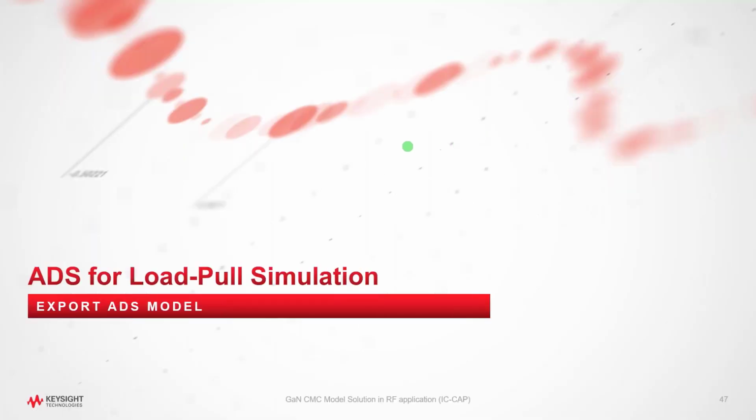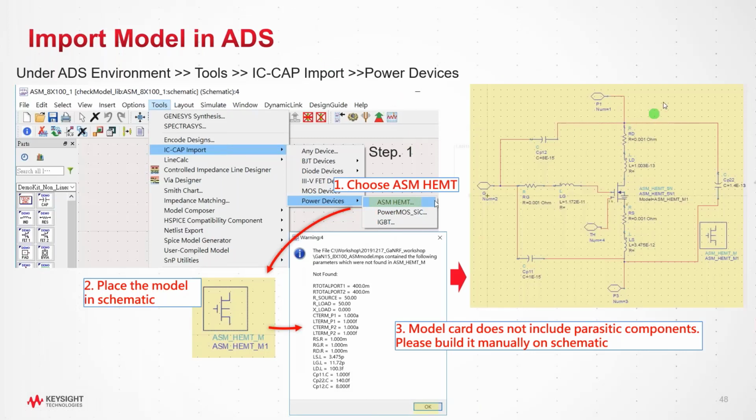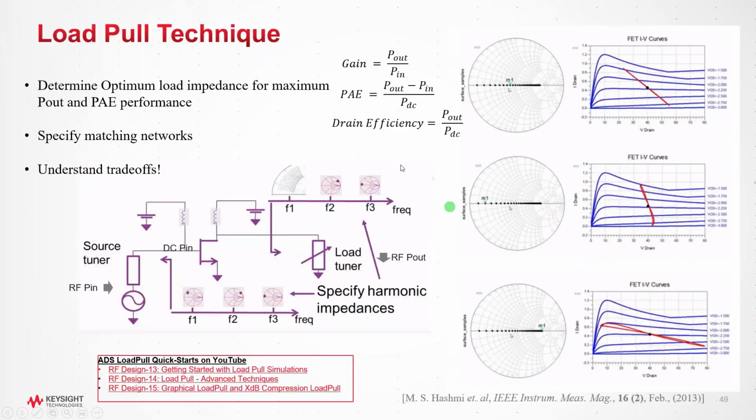All right, so as Abby said, if you guys can all see this, you can go into ADS and basically import that MPS, that model. Like if you did the ASM HEMT, and the MVSG has a similar extraction flow in IC-CAP, you just bring the MPS file, the model file, into ADS through tools in IC-CAP import. And that's going to bring in the intrinsic model. Anything parasitic that you want to put around it for your application, you have to do that.